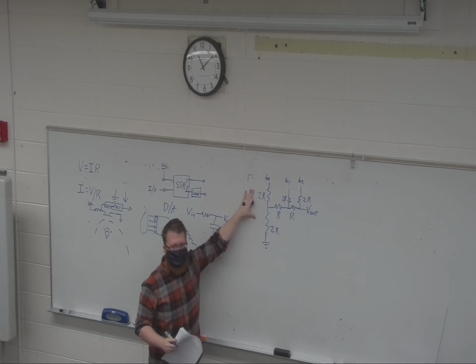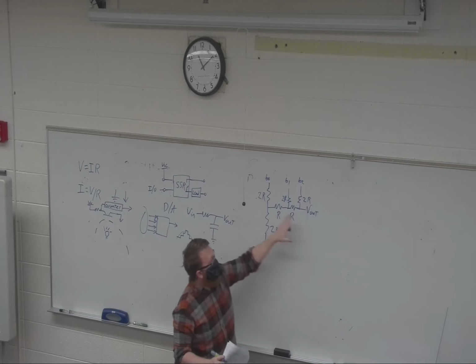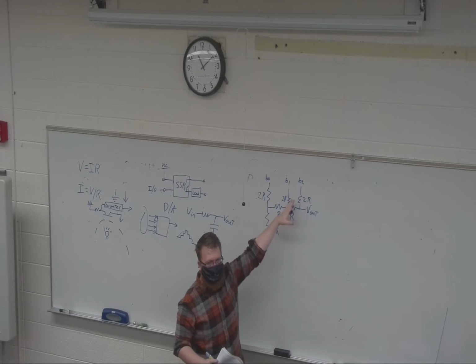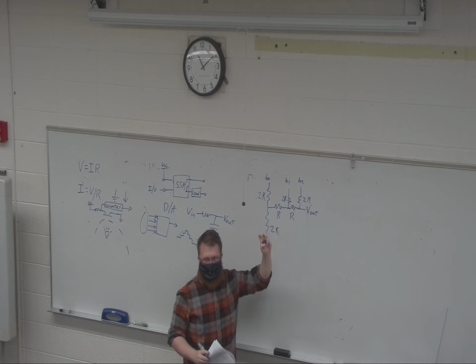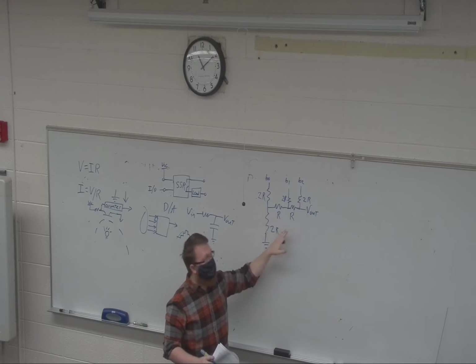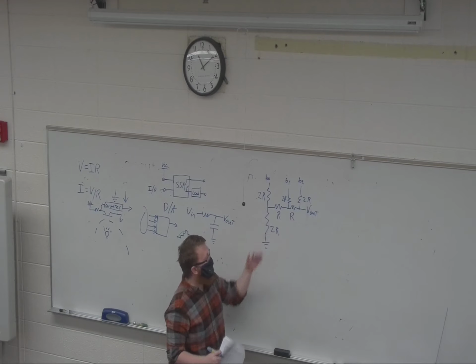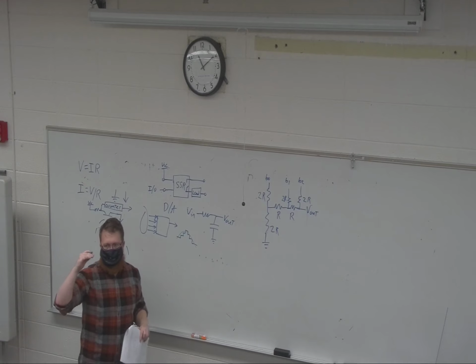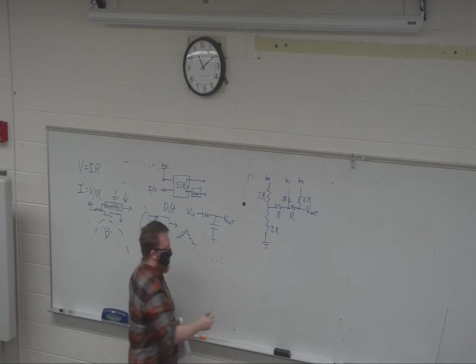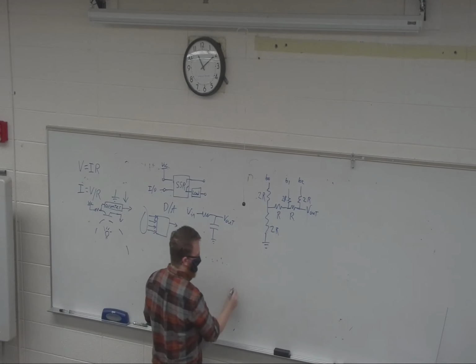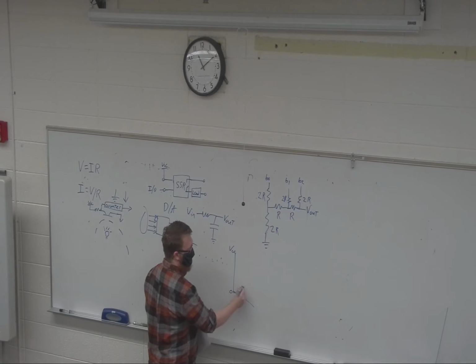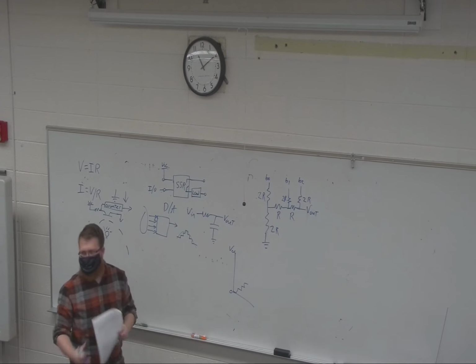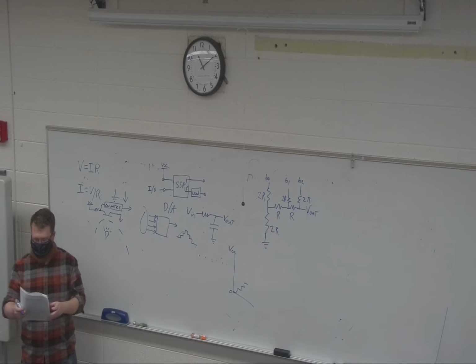And you can do some fancy Ohm's law calculations, which I won't make you do, to show that the output voltage, if all of them are 1, ends up being high, whatever the digital logic is. If they're all 0, it ends up being 0 because there's no power supply. And every step in between, as we count, every other digital combination outputs some voltage level between 0 and your supply voltage. So it's just going to step up. That's all a digital to analog converter is.